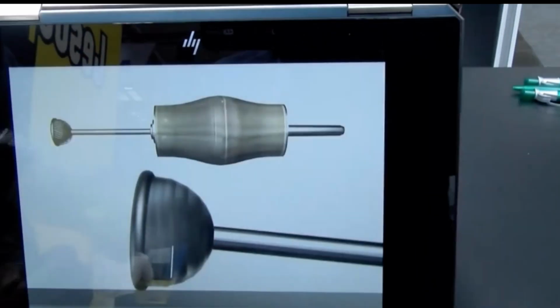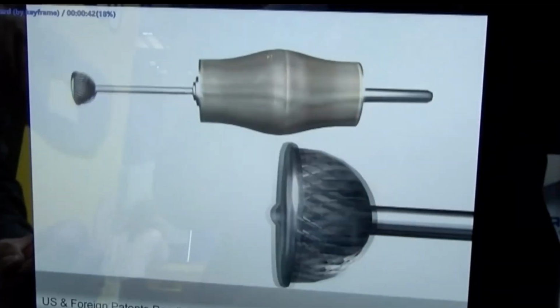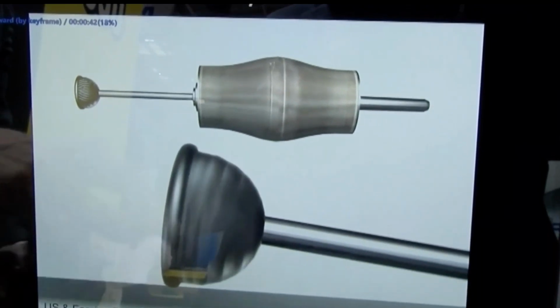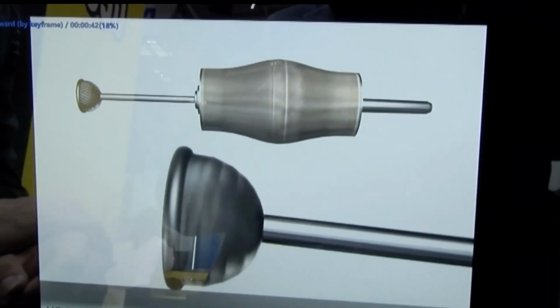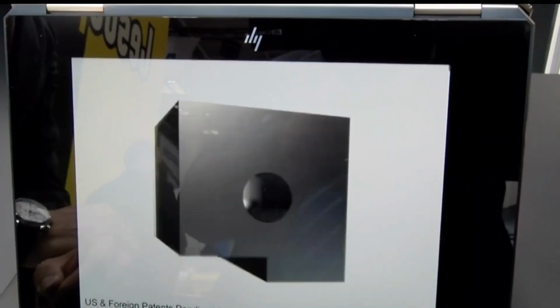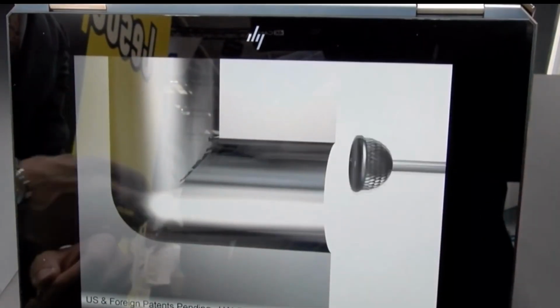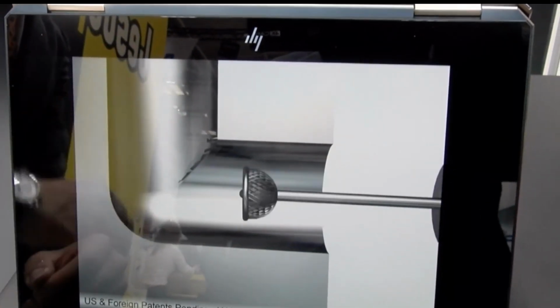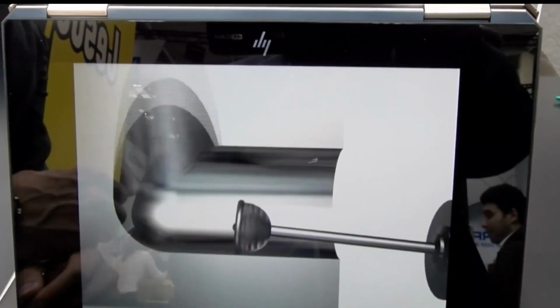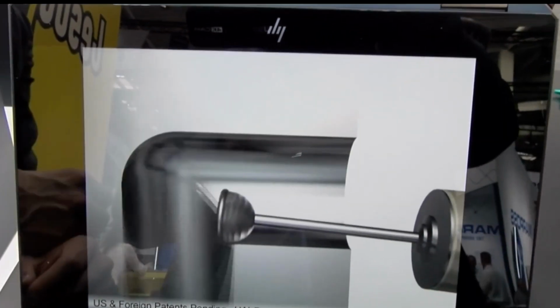Conversely, we can use the tool in a CNC setting. So here again, we see the protective ring on the end of the tool. The ring is riding along on the wall surface, and the carbide burr is never touching that wall. So in this scenario, we're going to see it in a lathe setting. The part is rotating while the tool is feeding in. Essentially, we're turning a thread. We're making a thread spiral on the inside of this hole.